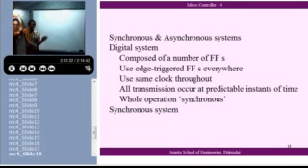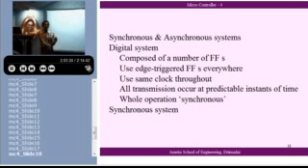The moment you have ensured that, in a synchronous system you can just run riot. You can put as many circuits as you want. In the asynchronous case, you are never sure whether it is 1 microsecond or 100 microseconds. So wherever your system is very small in size, you can afford to go in for an asynchronous system and cash in on that so-called improvement in speed. As the system size increases, you cannot do that. So wherever possible, as the system size increases, you go for a synchronous system. Is it okay?